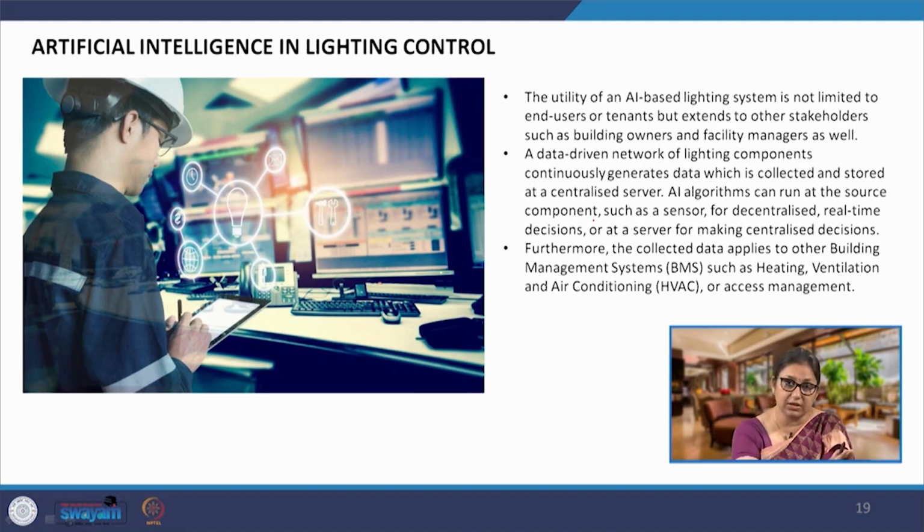As it goes further down, it may be 75%, and if it is below 100 lux, then we turn them on 100%. Plus, there could be sensors, which could be motion sensors, occupancy sensors, or here we are talking about the photo sensors. So, we can write programs to control how the lights behave.